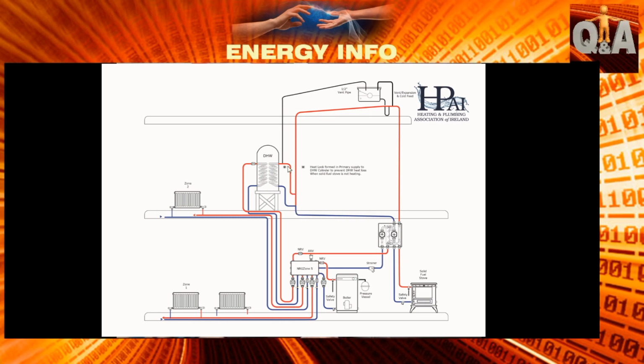But when the cylinder is drawing heat, the water heats, and so the water falls back down through the return and back down across the floorboards, back down to the stove. But if the stove ever turns off, the heat is trapped up inside the cylinder. You see, in that instance there's a half-inch vent pipe. That wouldn't be classed as an expansion. That's a vent that releases any air that might potentially get trapped in the coil.